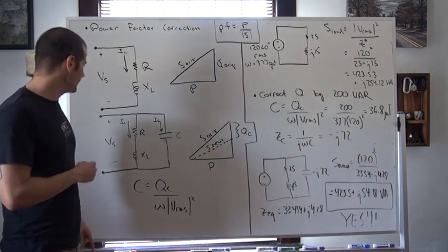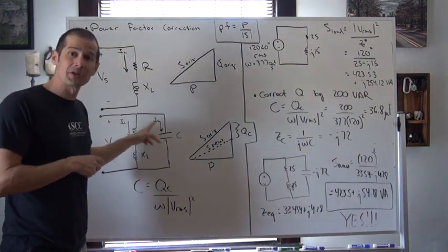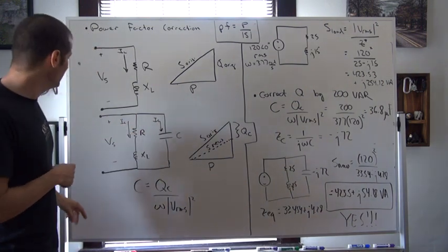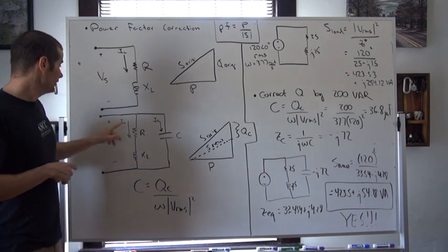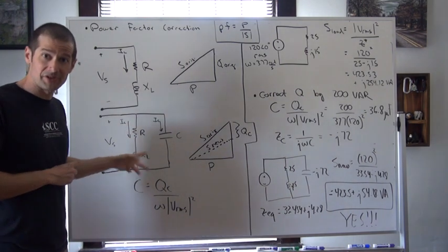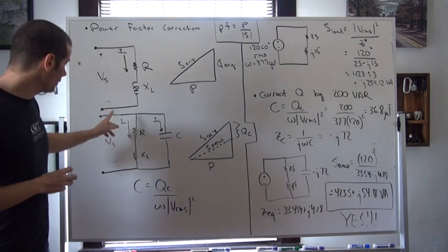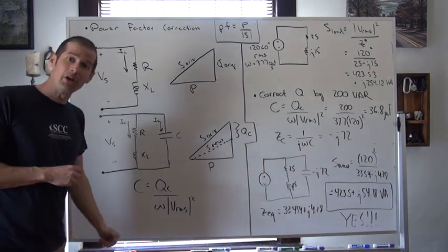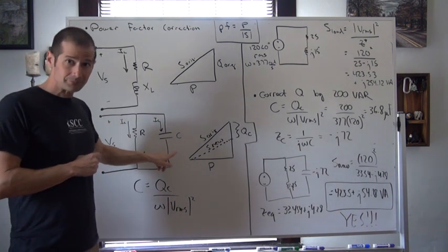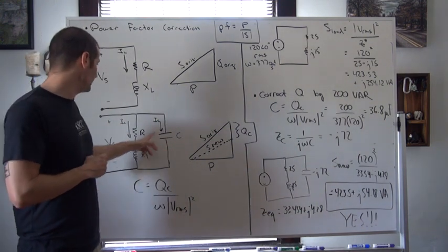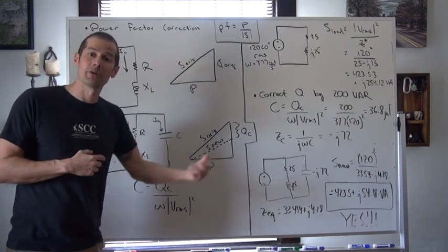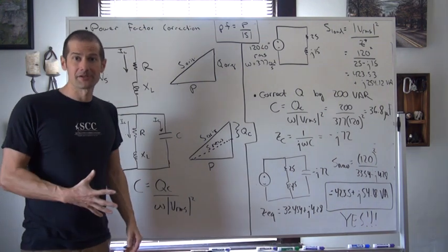So in this case, guys, if we hook a capacitor in parallel to that resistive inductive load, then we keep consistent that voltage across the original resistive inductive load, therefore also keeping the current through it the same. But by keeping that capacitor bank there in parallel, we change the amount of apparent power that's being introduced in the system.